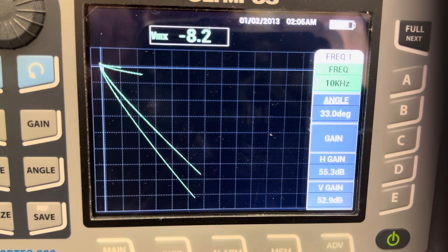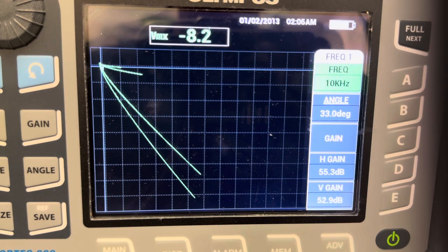So what do you think we're going to try to accomplish with this low frequency, larger coil? We're going to be trying to separate indications from those high conductivity materials that we couldn't separate with the high test frequency.